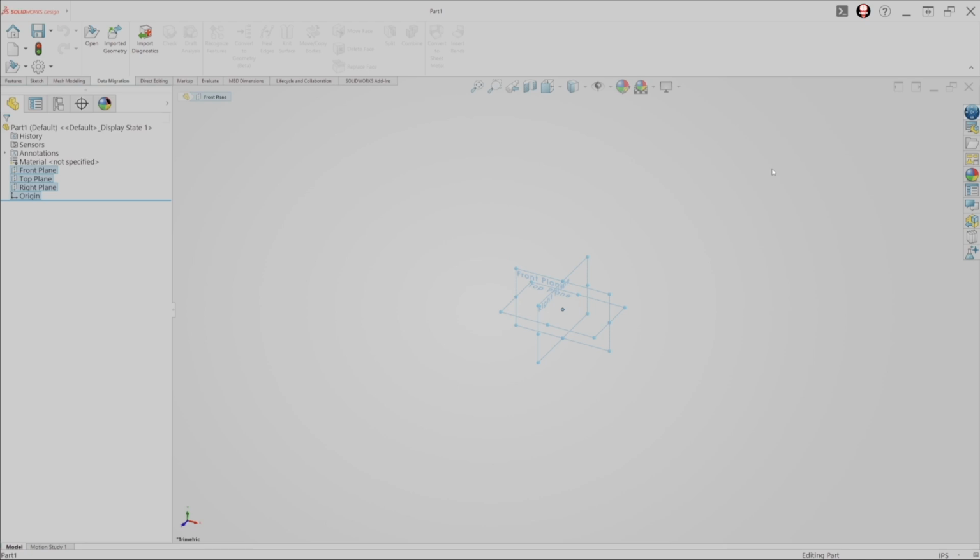Now that might work for prototyping or design review, but as soon as you want to use the part in assembly, machine it, or follow proper design for manufacturing practices or DFM, designing out in space can cause a ton of headaches. We always want to reference everything back to the origin. So we'll go over that more later, but for now we don't need to worry too much about it because our focus is understanding the buttons and how the system works. Later we're going to discuss proper DFM design in more detail.